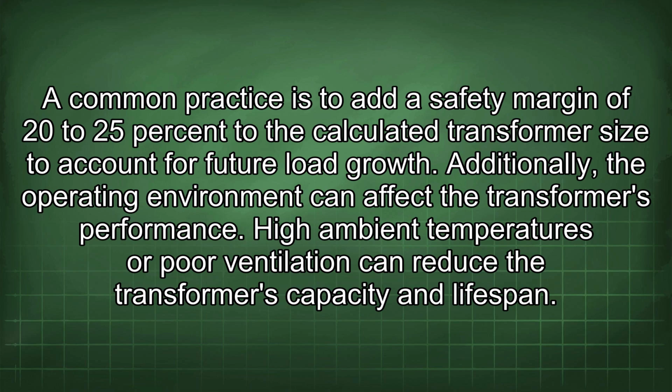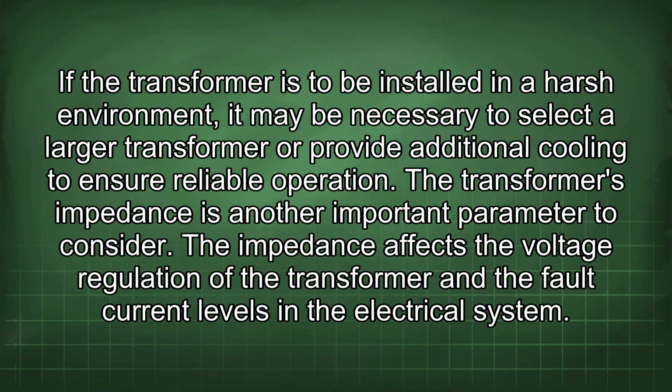High ambient temperatures or poor ventilation can reduce the transformer's capacity and lifespan. If the transformer is to be installed in a harsh environment, it may be necessary to select a larger transformer or provide additional cooling to ensure reliable operation. The transformer's impedance is another important parameter to consider.